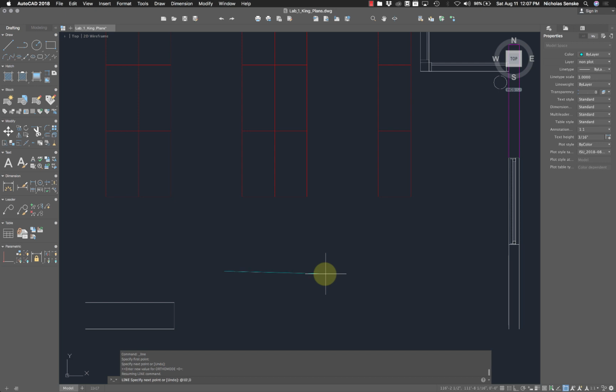So just like your coordinates in your high school geometry class, on the x coordinate, you're going 10 foot, and on the y coordinate, you're going 0. And then when you press enter, it's going to set a point. So now if I stop the command there by pressing return, I have a 10-foot line. Okay. If I wanted a line that's 5 foot tall, I would say @0,5 foot. And now that puts one of those in that space. Okay. So hopefully that makes sense.